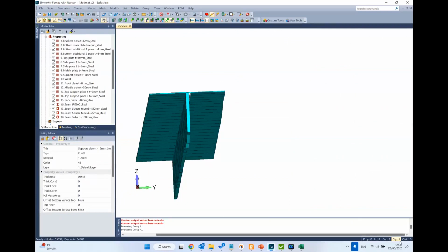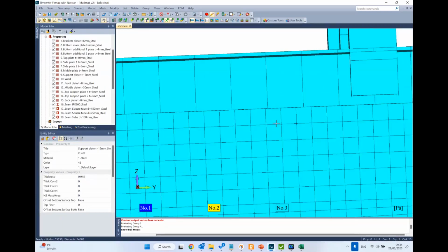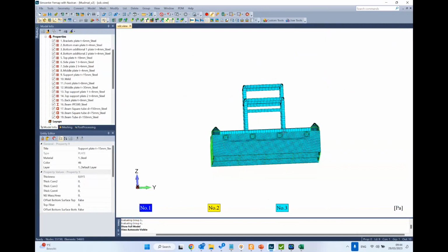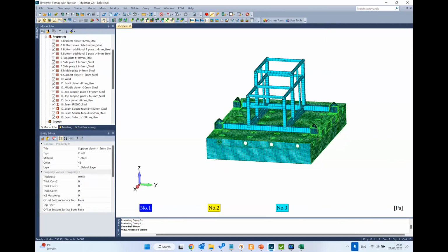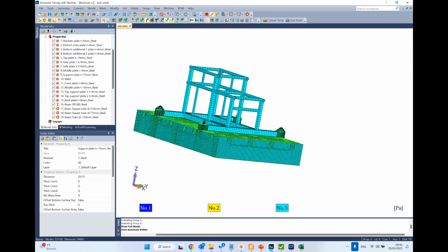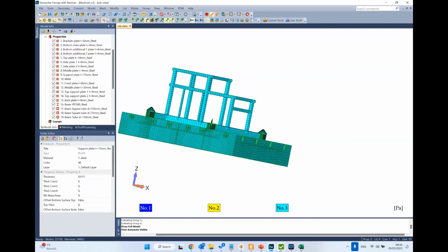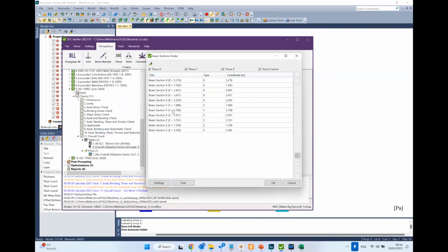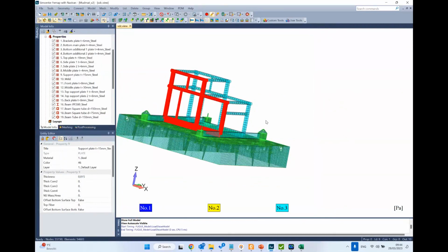So in our model here, we have, let's say in Y direction, a frame of elements, or in X direction laying within the same coordinate. So if I select Y 1.8 and click on preview, SDC Verifier will highlight what it defined.